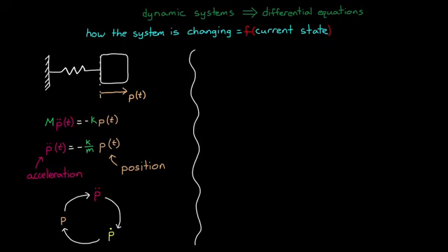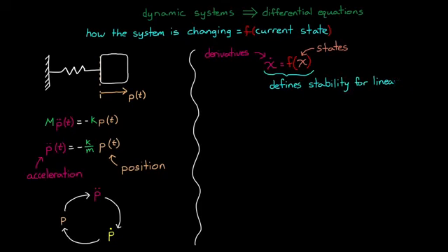For any arbitrary dynamic system, if we look at how the energy changes by analyzing the relationship between its states and their derivatives, we can make claims about things like the stability of the system. Is the energy being dissipated over time? Then the system is stable, and the faster the energy is dissipated, the more stable it is. If the energy is growing unbounded over time, even for just a part of it, then the system as a whole is unstable. Stability is an inherent property of a system simply from the way that the states and their derivatives are connected to each other.